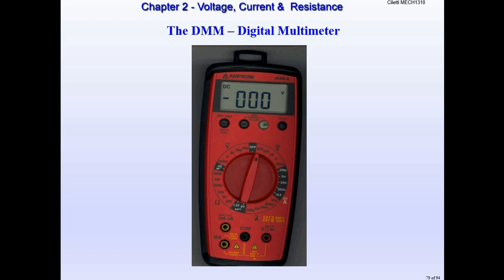We're going to go through this in class and learn how to use this stuff in our labs a little bit better, because it is important where you put the plugs in there. Notice there's 2 yellows, 1 red, and 1 black. Those all mean something. We're going to go through it. But we're going to learn how to use a digital multimeter in class to take readings and troubleshoot on the 870 trainer.